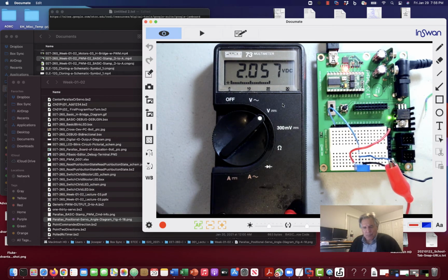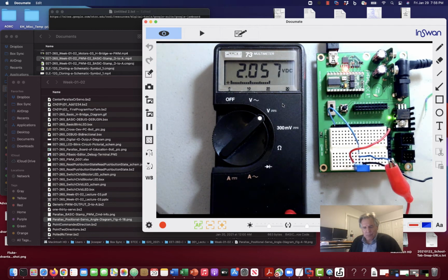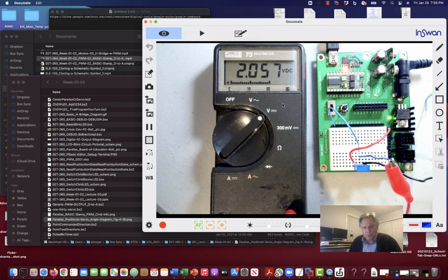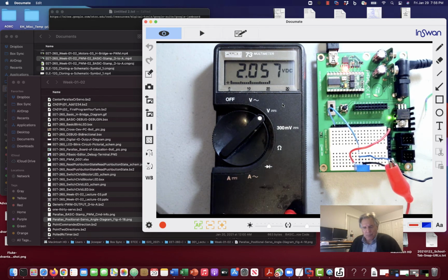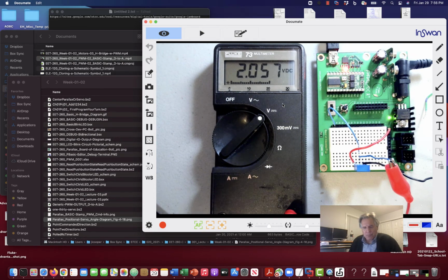Transistor logic inputs, whatever they're implemented in, whether CMOS or bipolar transistors. But if someone says that your digital input is TTL compatible, then it'll switch between a 0 and a 1 somewhere between, say, 0.4 and 2.0 volts. And we're going to find where that switch point is for our Basic Stamp, which designs its inputs to obey the TTL standard.